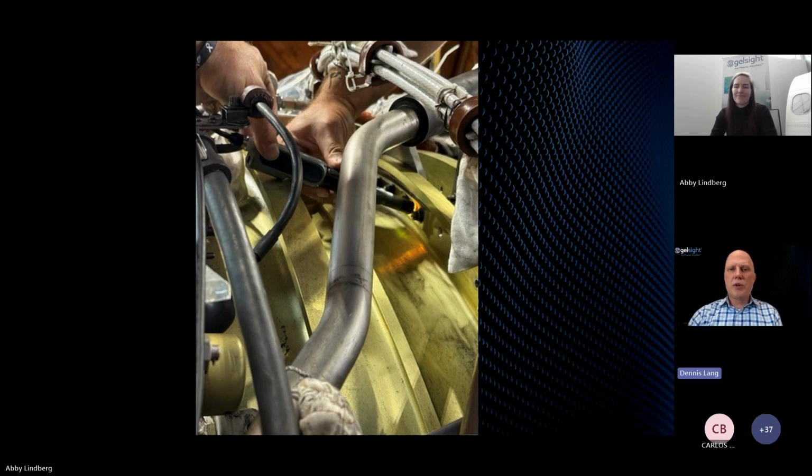The photo you see here is one of our early customer visits. We've had Modulus and been talking to customers directly with our systems for about a month. This particular one, you're seeing us on a CFAN engine doing an inspection around a fastener hole in an MRO or sustainment application. So, of course, when you pull a fastener out, there's a couple of different mechanisms that can create damage to the base material being joined, and that could be corrosion, whether that's galvanic or moisture-based or other kinds of things that corrode the material set, or just the movement of the parts in service.